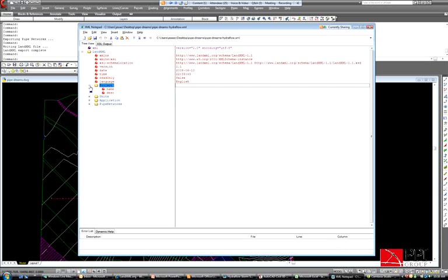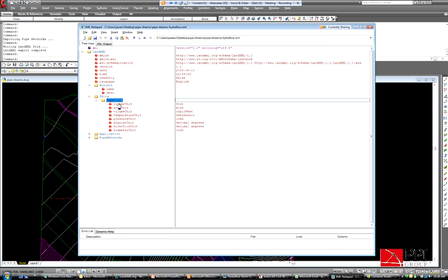So then, just coming down through here, I don't have a project name yet. One will come out of HydroFlow, you'll see. My imperial setting just shows you what units you're going to be using. My area unit is set to acres based on my drawing settings coming out of Civil 3D.